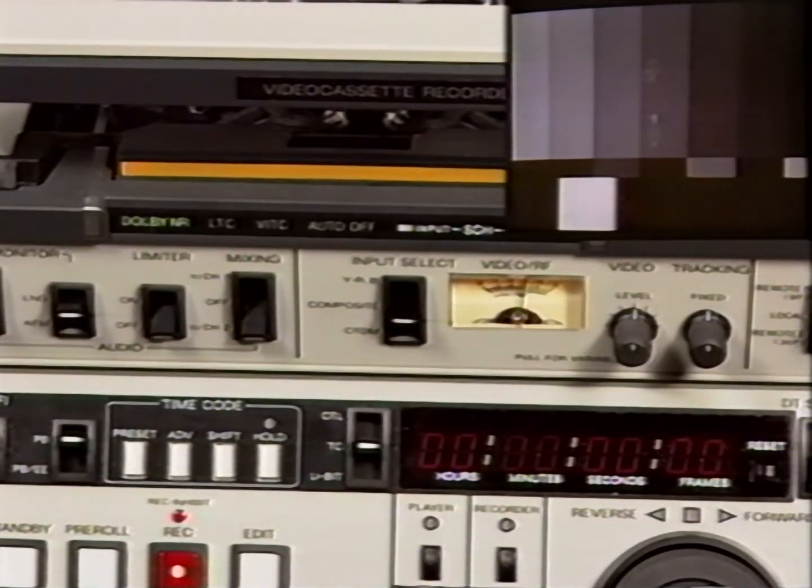Section 4. Video System. No chroma in composite mode. This is an example of a problem that exists in only one input select mode: loss of chroma in a composite mode. You can see that the front panel select switch is in the composite position when the problem exists.